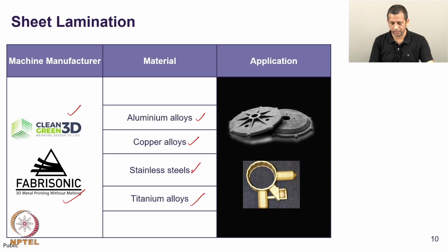In addition to that, even materials like carbon fiber composites can be printed very easily, and various metals, as you have seen here, can be printed, and if complicated shapes need to be formed, layered structures can be formed first and they can be shaped into the desired geometry as shown here.